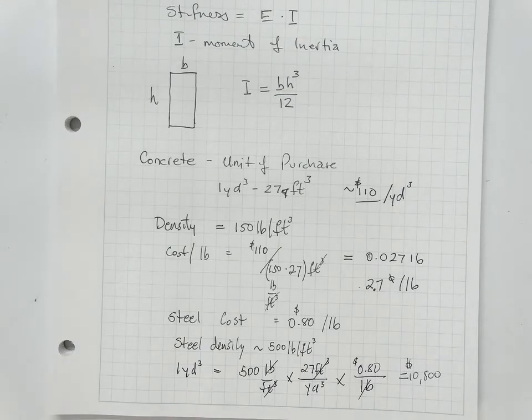It doesn't matter because the quality of the steel for reinforced concrete doesn't matter. So this is the cheapest kind of steel. Old washing machines, old cars, any recycled steel, just melt it in this furnace, draw it out as a wire, and roll the wire, or draw it out as a rod and roll the rod. You have reinforcement that's good for concrete.